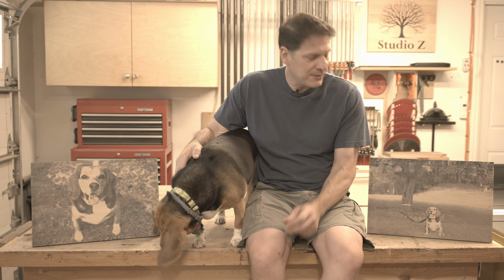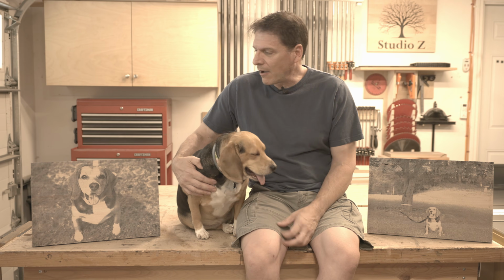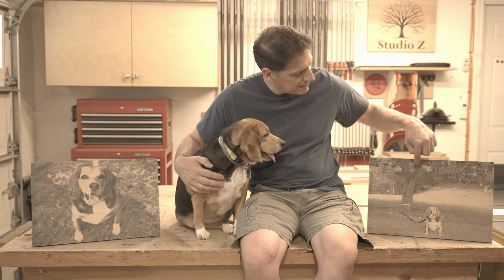And also the settings in Vectric. So the settings for the photo carving are really important. Messing around with the contrast, the brightness, all of that stuff, even the gamma will vastly improve how the pictures come out, especially getting in the dark details of certain photos. You can really bring them out and make a great photo out of it.